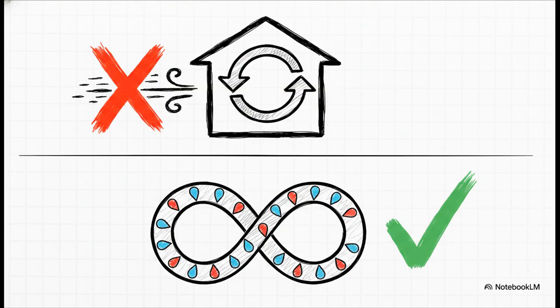Now, since we're looking at the mechanics, let's inject a little myth-busting energy here, because there are a couple of very common misconceptions about how this loop works. First myth: AC units pull fresh air from the outside to cool your home. Busted! No way! As we just learned, central air systems actually just recirculate your indoor air, passing it over those cold coils again and again. The outdoor unit just rejects heat. It definitely doesn't pump outdoor air inside.